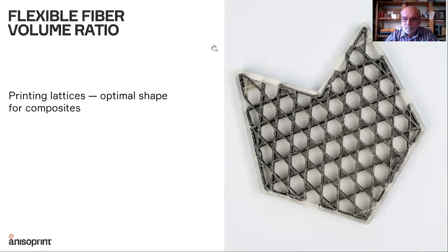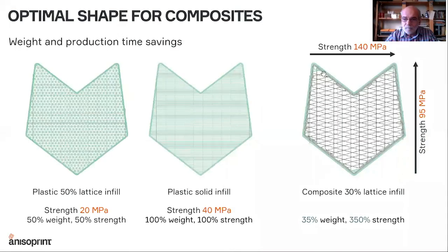They bring the best of composite material properties into the structures, simply because in lattices, every rib only works along the fiber, only works along the rib. So all the anisotropic properties of composite materials are fully realized. The material locally always works along the fiber and not across. Printing lattices is only possible with a co-extrusion.